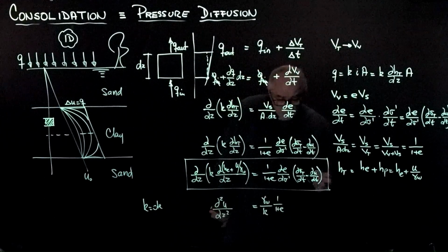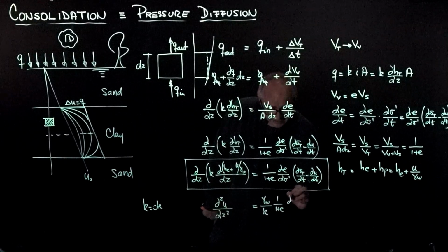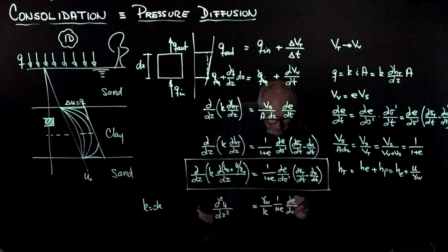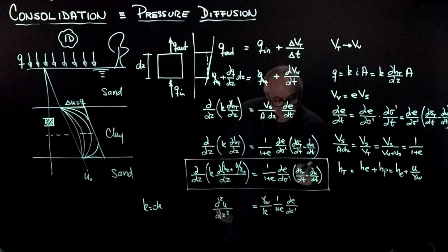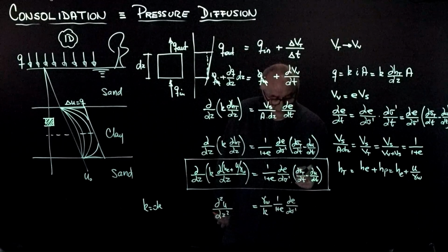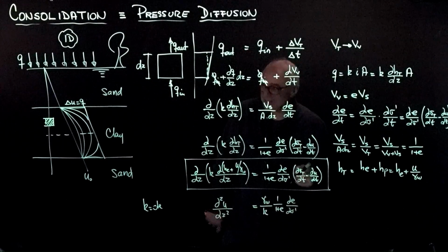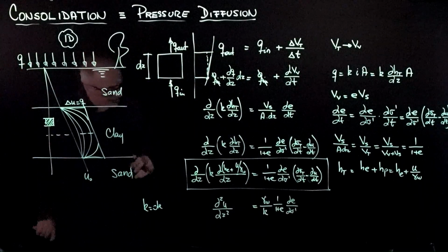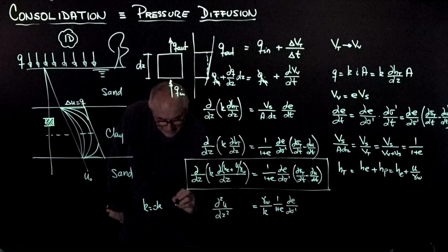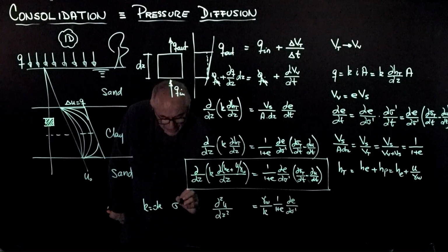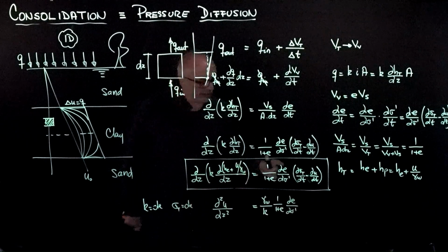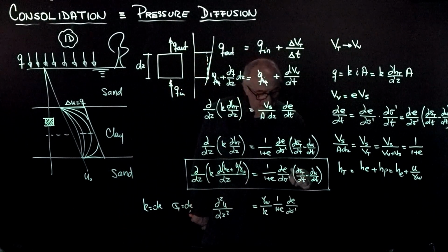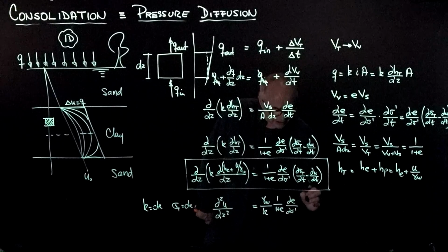And we can make one more assumption, so this is de over dσ effective. Let's assume that the load that I have applied does not change with time. So if in addition I make this assumption that the externally applied total load is constant, then this term cancels out, and I get minus du/dt.